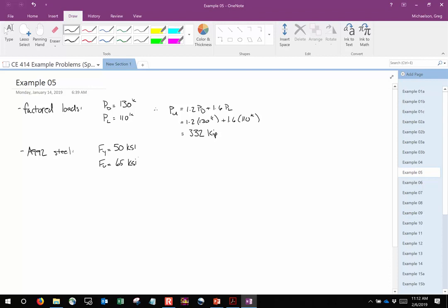Now, I want to point something out on this table. Does anybody notice these little gray and black and white squares next to the stresses? Did y'all notice these right here? What do those mean? If there's a black square, what does that mean? Preferred material specification, and then gray is other applicable material specification, and then white means it doesn't apply.